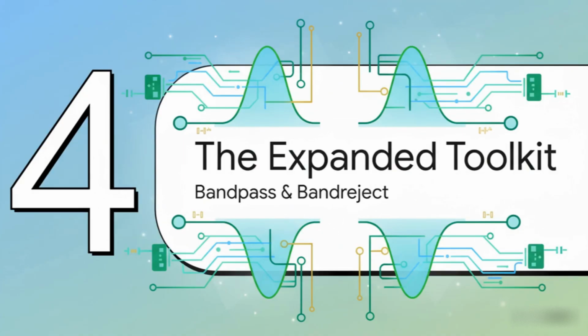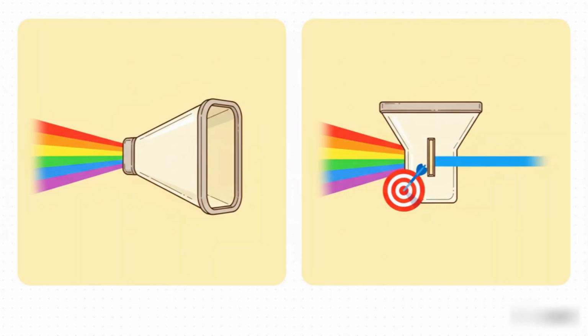So far, we've really only talked about low-pass and high-pass stuff. But the active approach opens up a whole new universe of possibilities. So welcome to Section 4, the expanded toolkit, where we look at band pass and band reject filters. See, with active filters, we can get super specific, creating filters that only pass or reject a very particular slice of frequencies. If you need a broadband response, to cover a wide range of frequencies, you can just cascade a simple low-pass and high-pass filter.